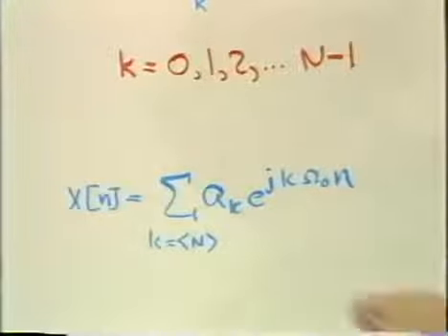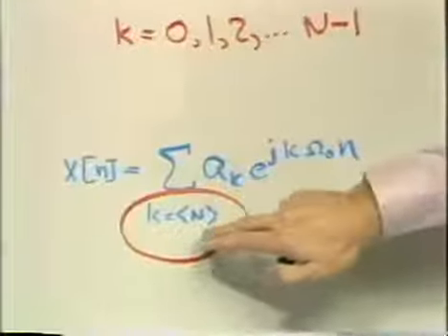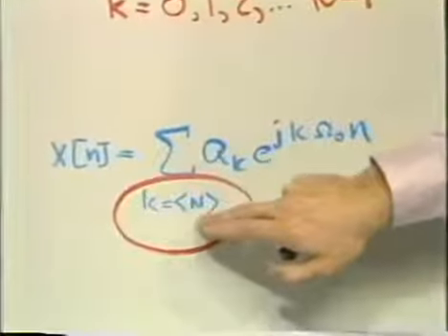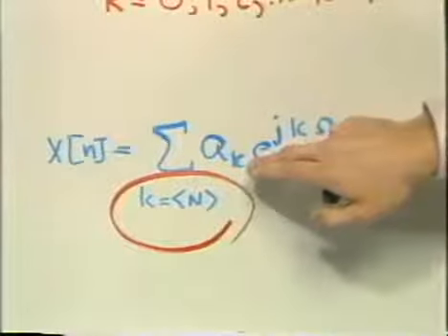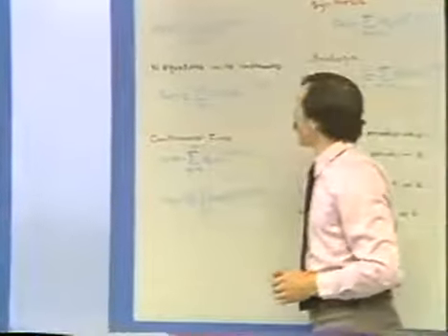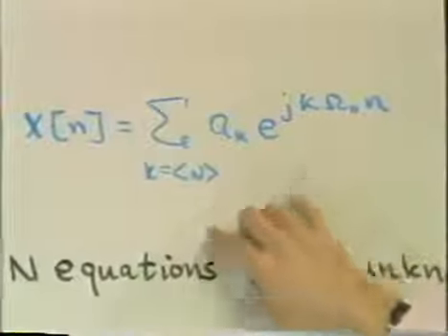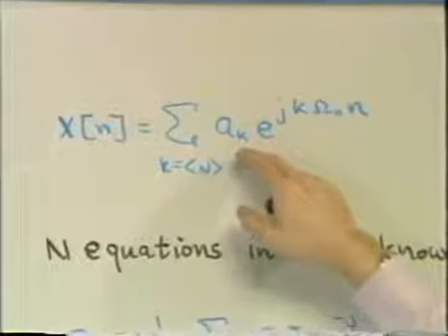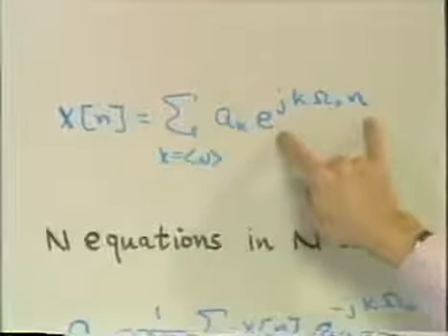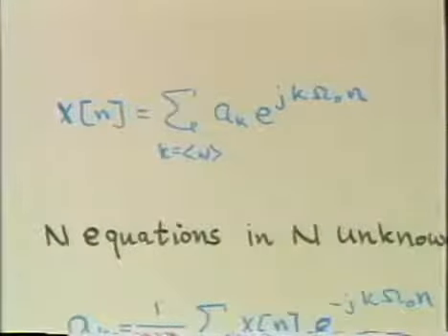This notation says that k ranges over one period of this periodic sequence, which is the Fourier series coefficients. Okay, so the expression that we have for the Fourier series, I've repeated here. The implication now is that the a sub k's are periodic. They periodically repeat because these exponentials periodically repeat. This indicates that we only use them over one period.